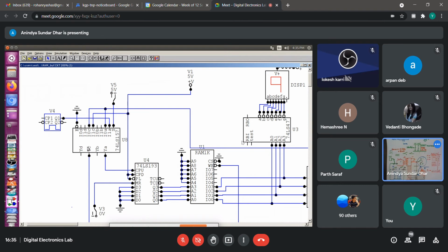So you see that pulsar will become active. Look at the pulsar connection. Pulsar is connected to I1A. What does that mean? It will be active when select line is what? Low. No, yes, I1 means when select line is 1, when it is high. So at that time, when S is high, you see I am talking about this output C. There are two input lines, I0C and I1C. So when select line is high, that is at the read mode, I am connecting it to the power supply so that it will never go into the write mode again. Again means if I press the ASCII keypad, it should not enter into the write mode.